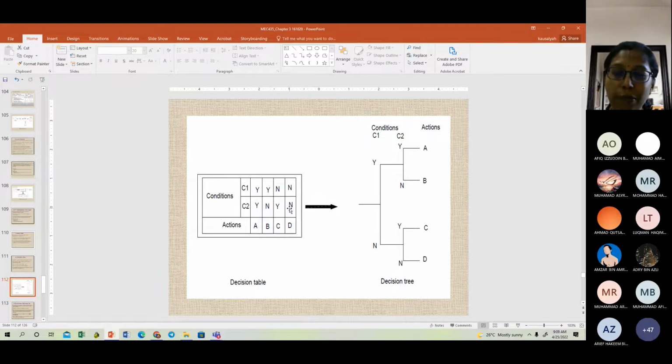So you understand a mismatch: switch on of a machine, switch on of lubrication, switch off a machine, switch on of lubrication for cooling. So like that, basically this is what you do in programming. You give if and or, so this kind of setups, all right? So we will decide the type of actions, and then based on this, we will actually program and key it into our machining setup. So it will automatically detect and it will run the sequence. So you use something called the decision table, which can be actually converted into a decision tree. So what's the difference between both is just the presentation method.